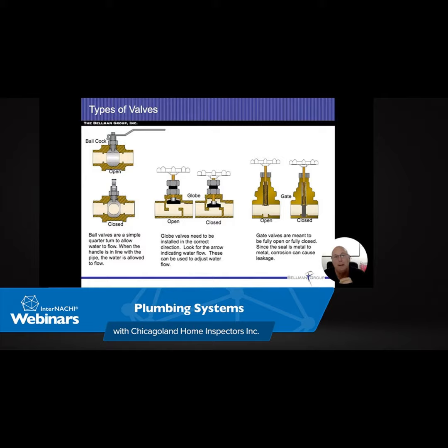Direct venting, I made that mention before. For within 5 feet, typically we're not going to have too much of a problem with it. Anytime you're suspicious of it, though, you should fill up the sink and give it a good drain and see if there's any sort of problems. You don't always know what's going to be behind the walls.